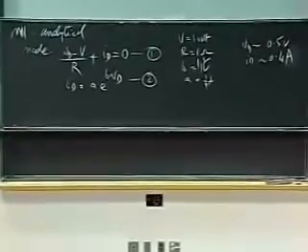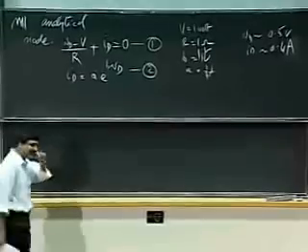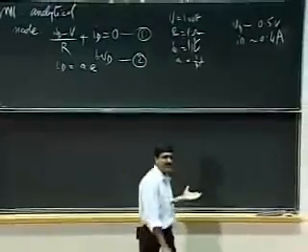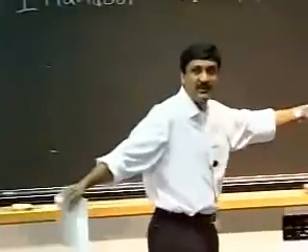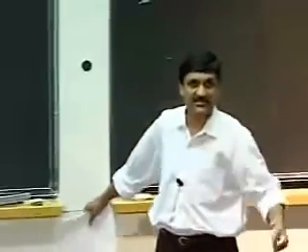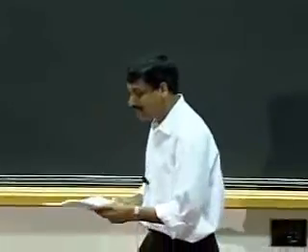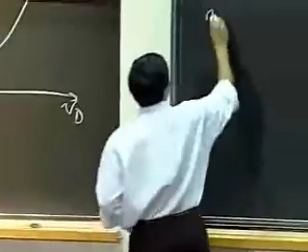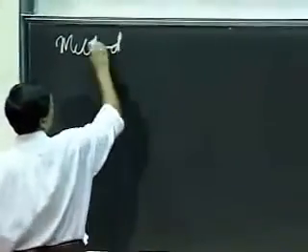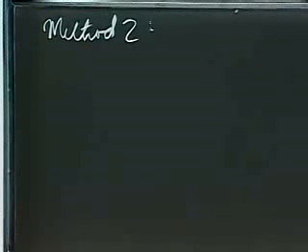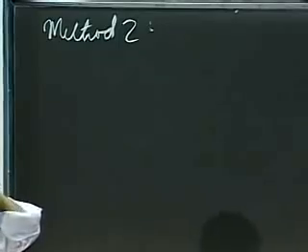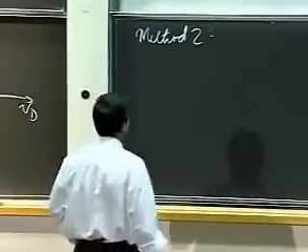As I said, there's not a whole lot to it. Whether it's a nonlinear circuit or a linear circuit, as long as I'm inside this playground where the lumped circuit abstraction holds, I can apply my node equations and then go ahead and solve it. Let me show you a few more methods so we can articulate your repertoire of tools for nonlinear circuits.